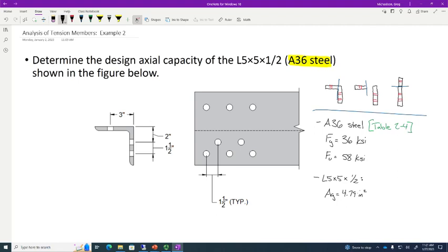Now there is a property that you're not necessarily going to look up, but we're obviously going to need to compute net area. The effective bolt, well, we can get that from the bolts. I'm talking about from the angle: what else do you need to compute a hole diameter or a hole area? The thickness, right? There's nothing to look up though. What is the thickness? It's a 1/2 inch. For angles, the thickness is just what it's listed. So we need the thickness.